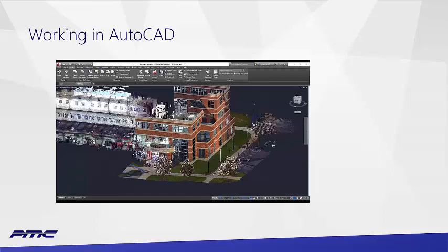I wouldn't recommend doing that. I would shut that off. It's far better to just simply draw on top of the point cloud and visually align things up. That goes back to that discussion we had earlier over accuracy. What do you do when walls aren't straight and things like that? You're going to want to make some decisions.